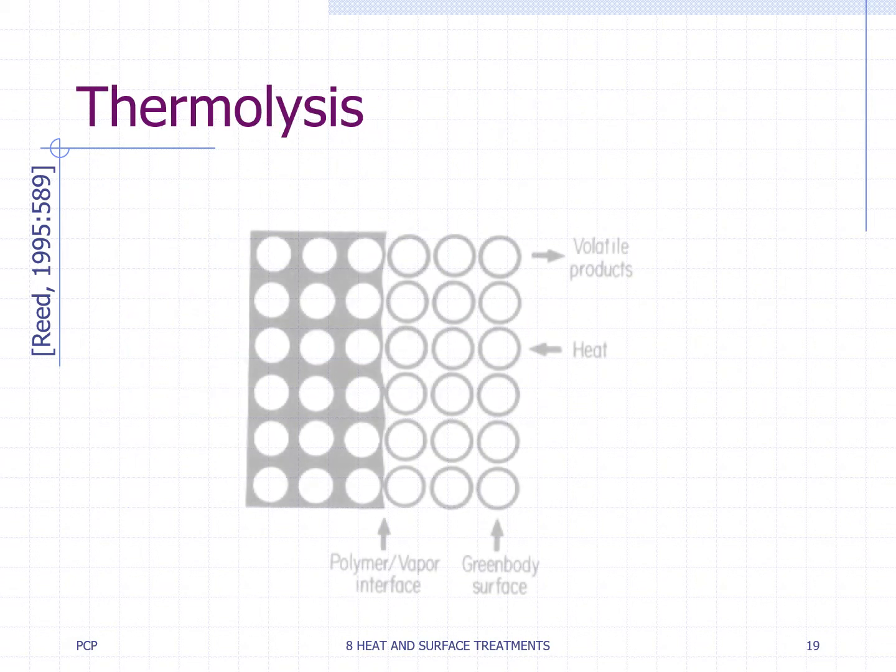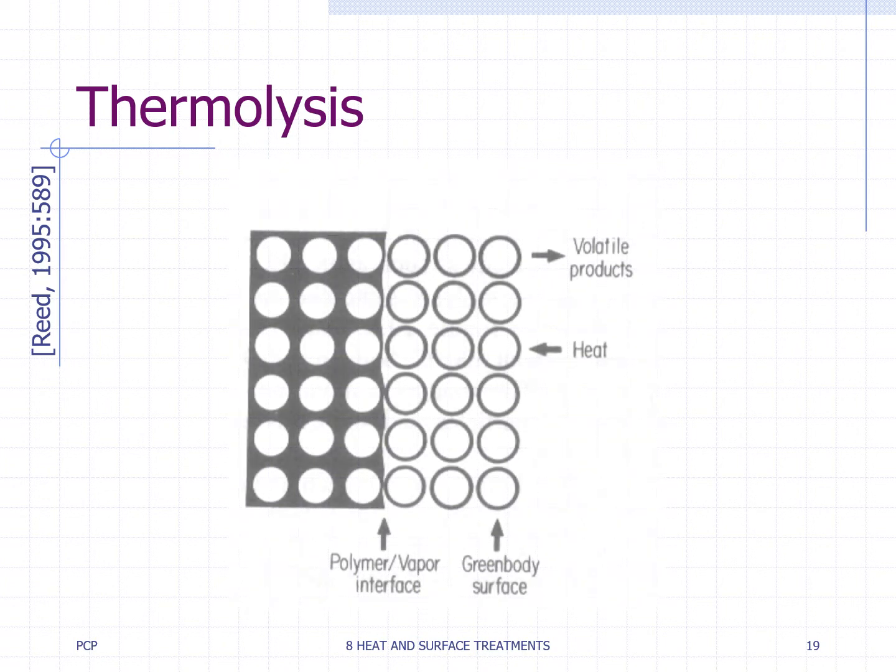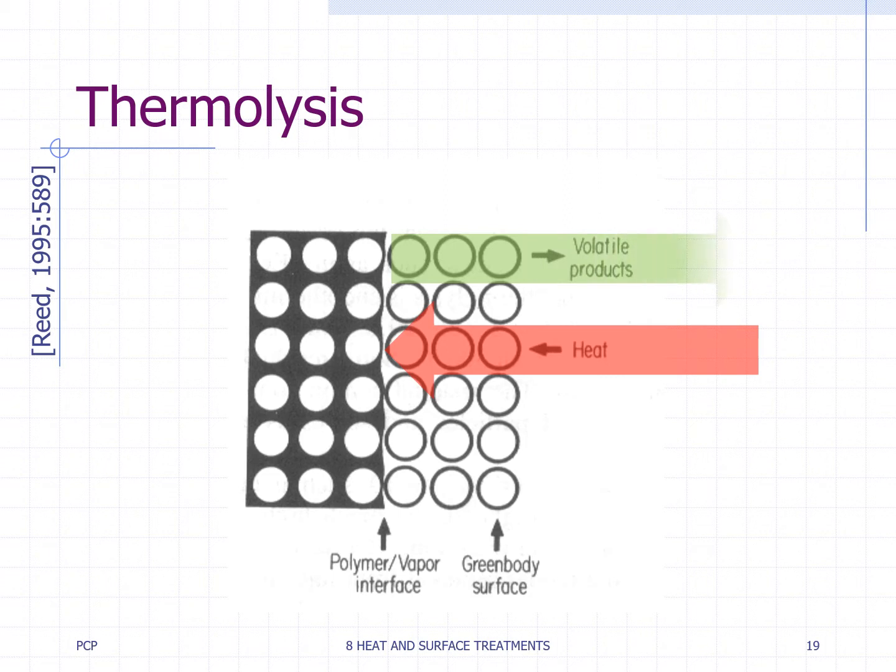Thermolysis, debinding or organic burnout, is an important step prior to densification or sintering. Incomplete binder removal and uncontrolled thermolysis may introduce a new population of product defects. Binder burnout is very dependent on the composition of the binder material and the composition and flow of the gas surrounding the product and in the pores of the product.